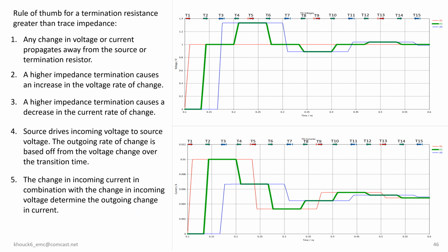In this visual representation, voltage and current measurements are depicted at three critical junctures along a trace: the drive, midpoint, and termination. Each specific time marker corresponds to the arrival or traversal of the evolving field wave along the trace. The red line and arrow signify the drive source, symbolizing the initial point of signal injection. The green line and arrow denote the midpoint of the trace, providing understanding into how the signal behaves as it traverses the trace.